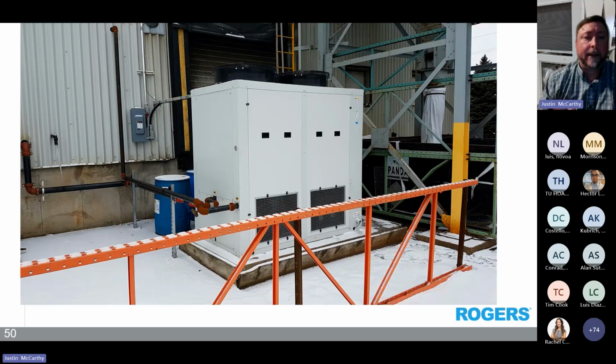Right here we have a chiller which is operating in low ambient. So obviously northern US down to mid US. What you see there, in the summer, those would be an expanded panel right there. Those are called winter panels, and they reduce the air going across. And also we're slowing down these fans with temperature.